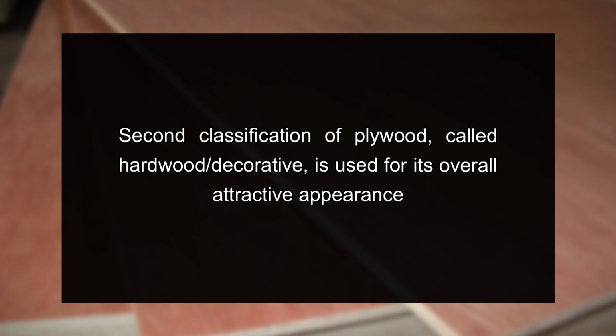For example, plywood used for subflooring in a house is rated interior CD. This means it has a C face with a D back and the glue is suitable for use in protected locations. The inner plies of all construction and industrial plywood are made from grade C or D veneer, no matter what the rating.